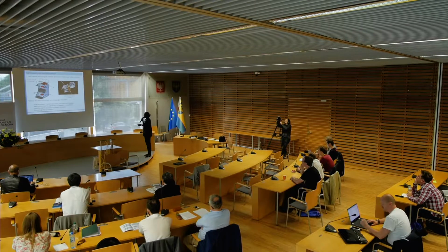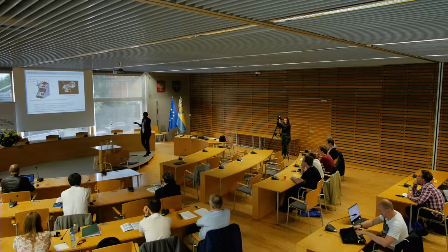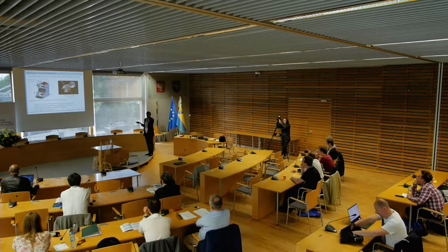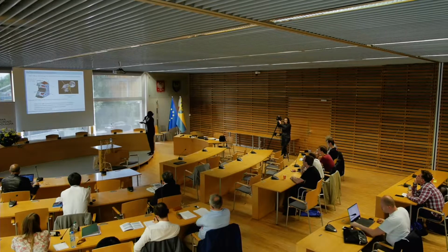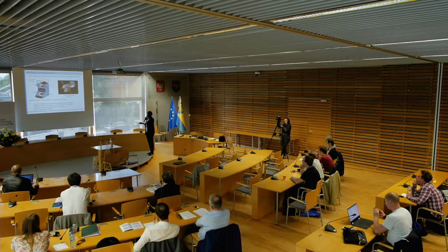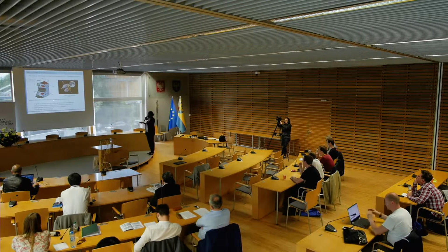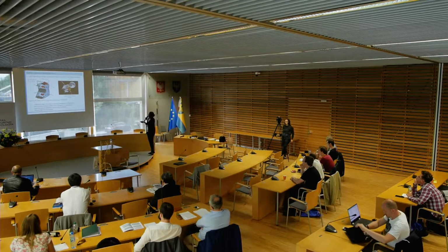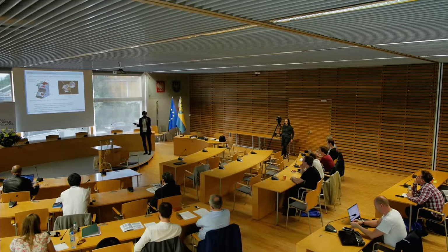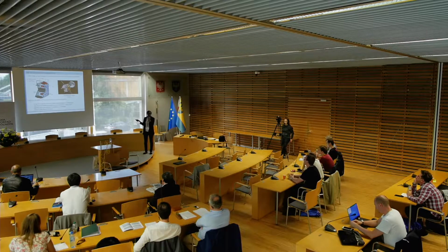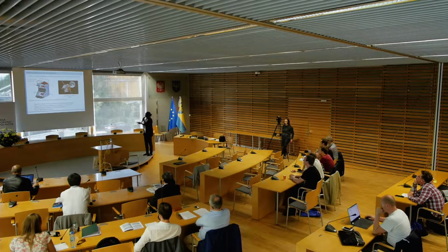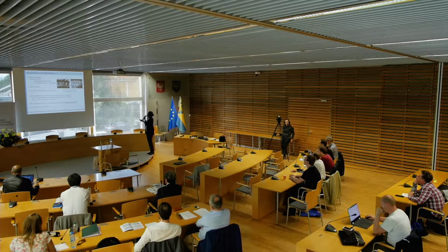to chemical propulsion. Today, these technologies are very widely used on board telecommunication satellites to adjust for their positioning and attitude control. And increasingly, there is a march towards what are called all-electric platforms, which are equipped only with plasma thrusters. There are also a lot of ambitious projects recently launched, for example, just a few months ago by SpaceX and OneWeb, using satellite swarms with this technology. And in the future, we hope to develop very high thrust models, not only Hall thrusters, but also other plasma propulsion technologies. So there are a lot of challenges associated with this technology.